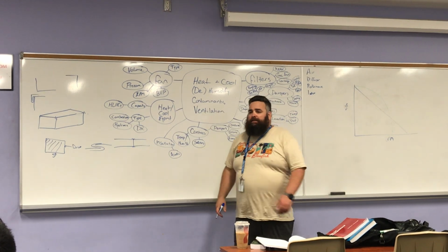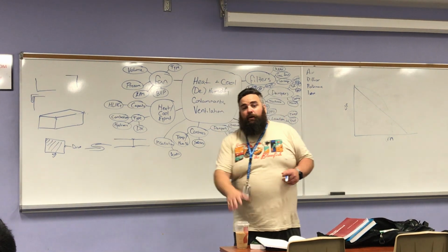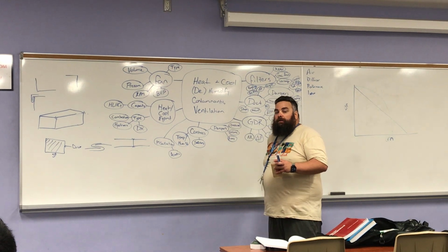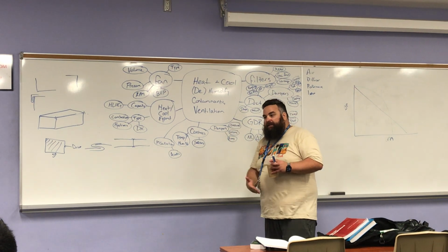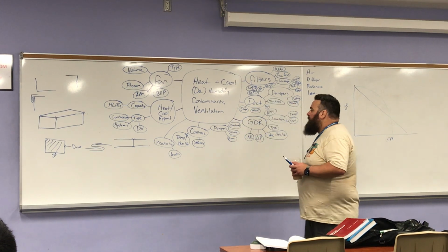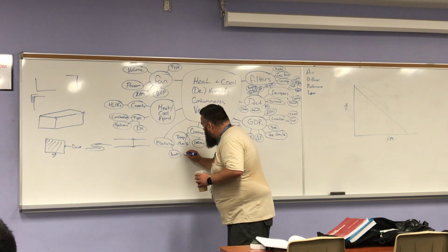How could that impact my duct system? Make it quieter. It'll certainly make it quieter, but what else? Also more air pressure drop. Pressure drop, right? The fibrous lining inside a duct is not as smooth as the duct wall itself, so we're going to have an increased pressure drop. So we can do that. Delta P.